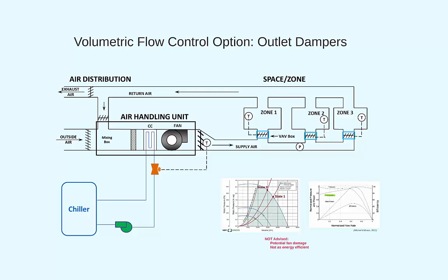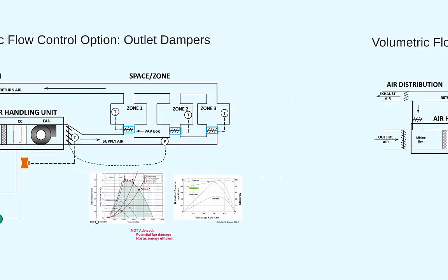So again, if the VAV damper closes and the static pressure in the supply duct increases, we could have that additional damper on the discharge side of the fan start to close in order to maintain a static pressure set point. This type of configuration still just changes the system curve, and we ride the fan curve back a bit. But now a good part of the pressure being dissipated will occur at the discharge air damper just downstream of the fan, out of earshot of any space occupants.